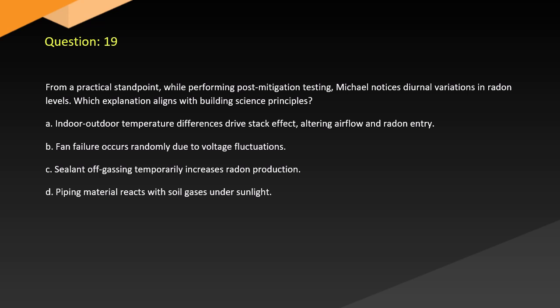A. Indoor-outdoor temperature differences drive stack effect, altering airflow and radon entry. B. Fan failure occurs randomly due to voltage fluctuations. C. Sealant off-gassing temporarily increases radon production. D. Piping material reacts with soil gases under sunlight.